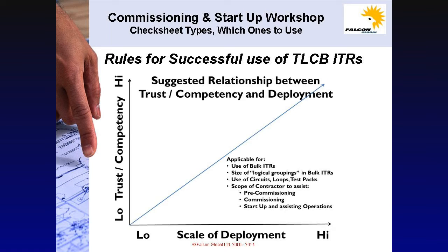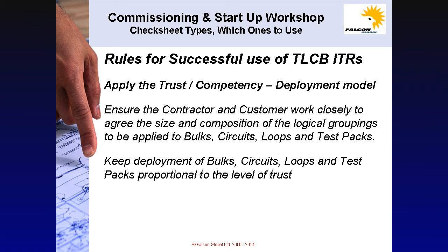Use the relationship between the competency, trust and scale of deployment model. Rules for the successful use of test pack, loop, circuit and bulk check sheets, the TLCB ITRs. Apply the trust, competency, scale of deployment model. Ensure the operator and contractor work closely together to agree the size and composition of the logical groupings to be applied to bulks, circuits, loops and test packs.